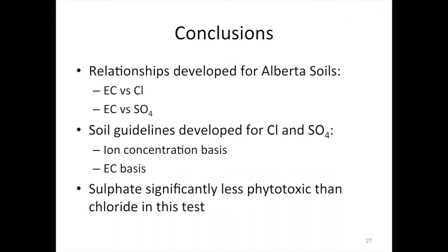We developed soil guidelines both on an ion concentration basis and an EC basis. And we concluded that sulphate was significantly less phytotoxic than chloride in our battery of tests. And therefore, the corollary of that would be that it would be a reasonable approach, if you're dealing with a site where you know the salinity is all sulfate-based, to take perhaps a different approach from just the straight chloride-based toxicity approach.